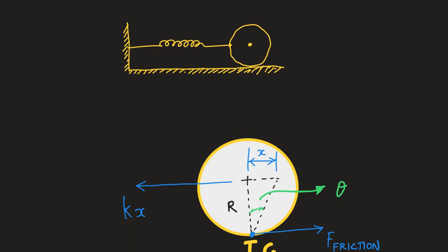And why is there an instantaneous center? That comes from the assumption of rolling without slipping. So see, this is how the concepts come stacking one after the other. That makes the subject so beautiful. So now x, the deflection in the spring, can be related to this particular rotation of the radial line. It is pretty simple. Little x is equal to capital R times theta.